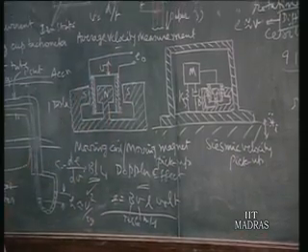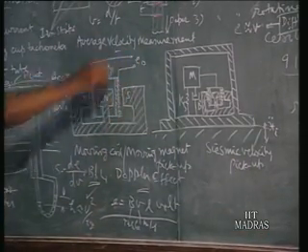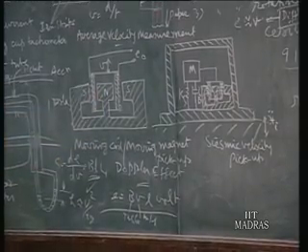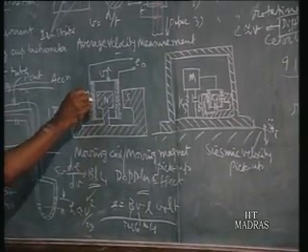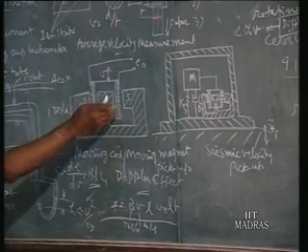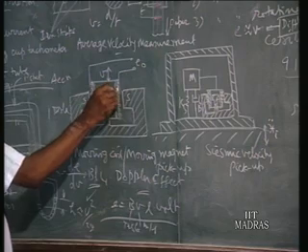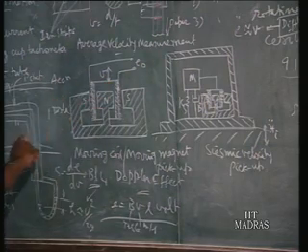The weight of the coil increases. Suppose you have connected the coil to the moving body, then it becomes a loading effect. The velocity may be dampened. So to reduce L, we want to have a smaller mass. For a given mass, if we want to have a larger length, then reduce the cross section of the wire and have a longer length.